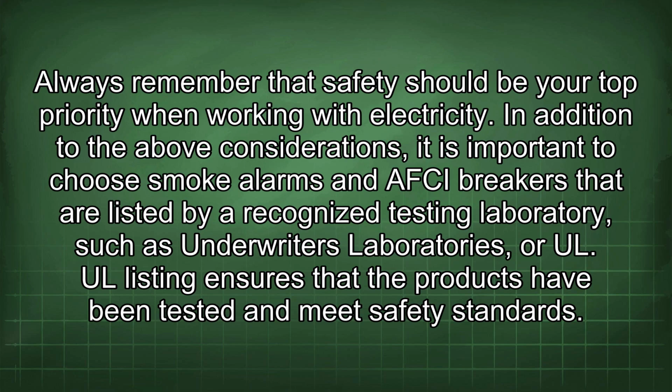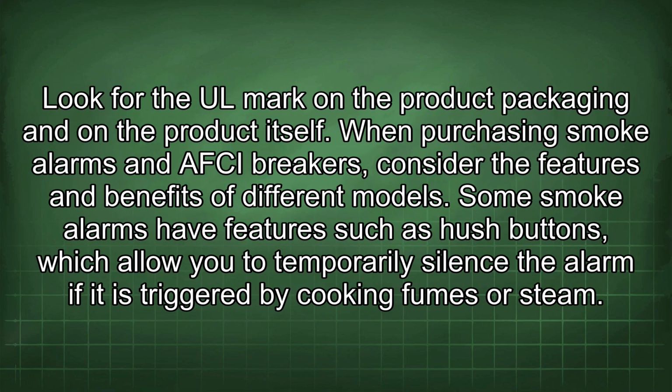In addition to the above considerations, it is important to choose smoke alarms and AFCI breakers that are listed by a recognized testing laboratory, such as Underwriters Laboratories or UL. UL listing ensures that the products have been tested and meet safety standards. Look for the UL mark on the product packaging and on the product itself.